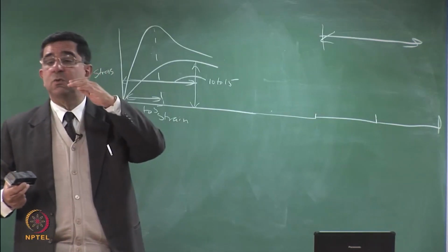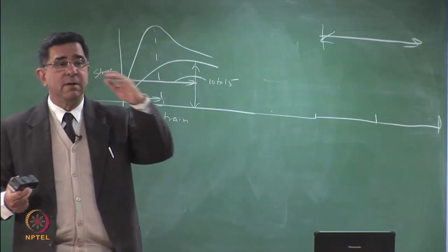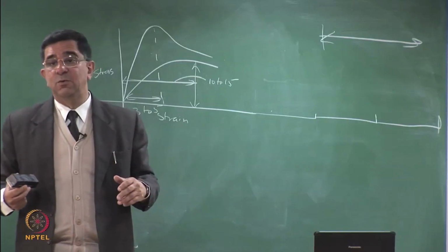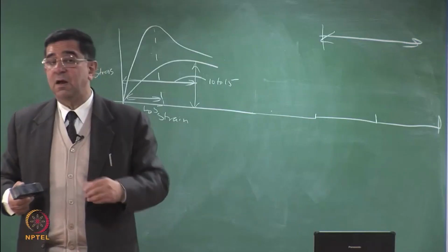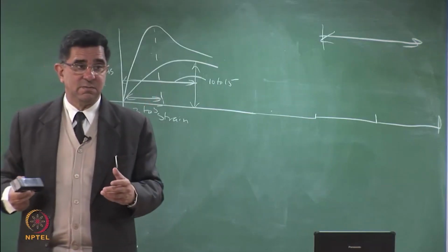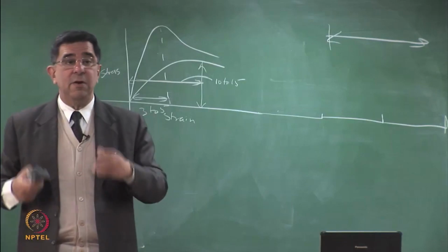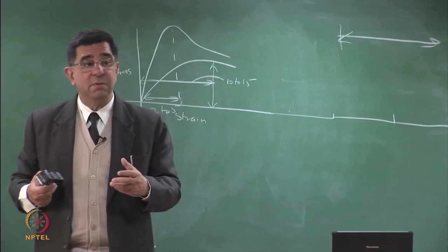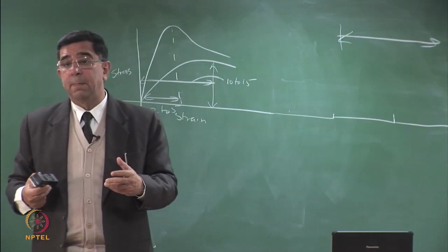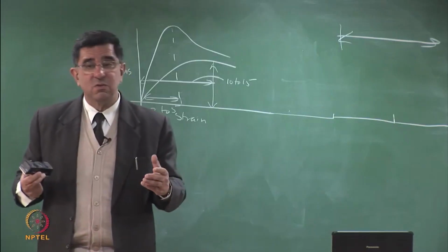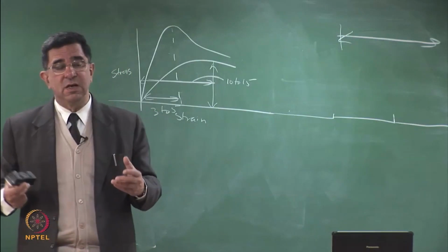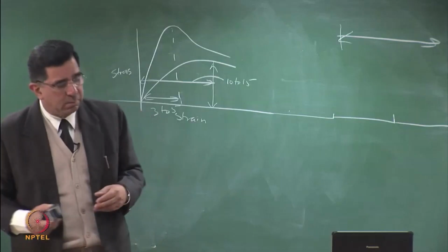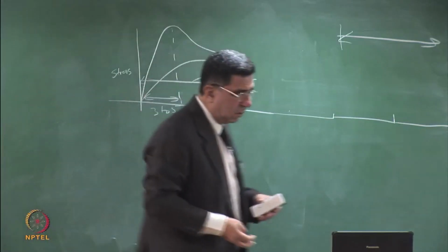So maybe which has more settlement, cover or liner? A liner has more settlement because the stresses are higher, but a cover has more settlement because there is biodegradation. So in municipal solid waste landfills where the biodegradable content is higher, cover settlements can be very large. But if you have inorganic waste which does not settle due to biodegradation, then maybe the liner settles more. But if you are going to have very large settlements, then you will use LDPE polymer. Okay, so